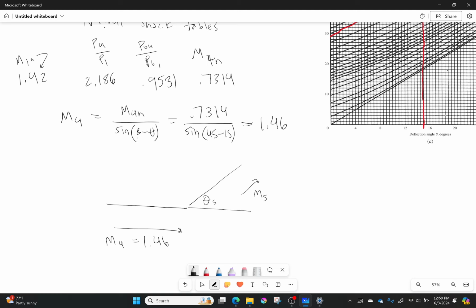Well, let's do some math. So first off, if I'm doing it based on my shape right here, I've got 5 degrees for the half angle there and 5 degrees there, which makes this 170 because it's an isosceles triangle. And so that means that this angle right here is going to be 10 degrees. So theta 5 is equal to 10 degrees. Beyond that, everything is exactly the same for us. I can go ahead and do the problem just like I've done all the other Prandtl-Meyer sections in this problem. So let's figure that out and get it going.